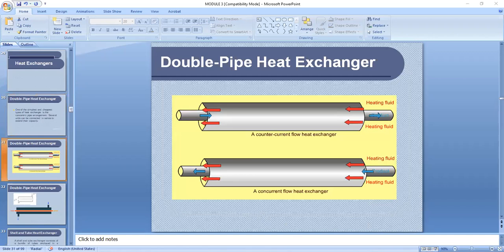So it can either be in countercurrent manner or co-current manner. So countercurrent, meaning the heating fluid or the cooling medium is facing the feed to be cooled or heated. So flowing countercurrent to the feed that is to be cooled or heated. If it's co-current, they enter the same side of the heat exchanger. Same thing with the side where they're leaving the said heat exchanger.